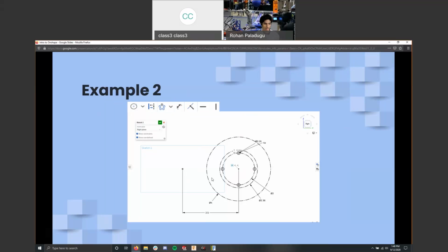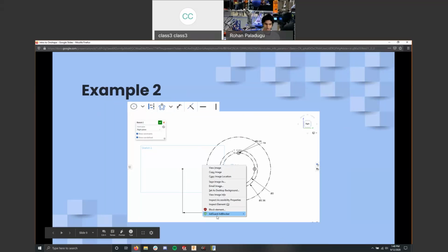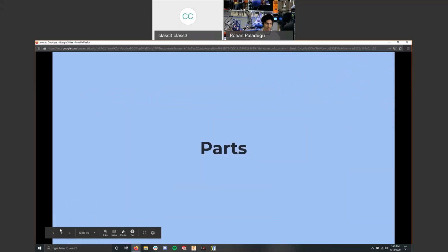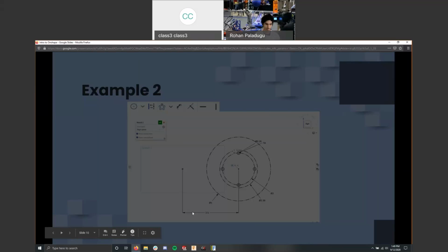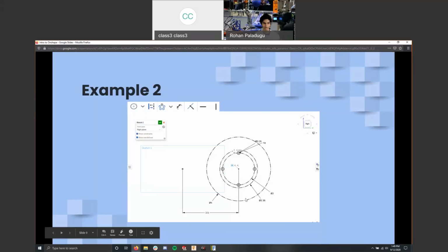And you can see that I dimensioned this off from the origin, which is this little dot, 3.5 inches. Sorry, 3.5 inches. To make sure that it stayed perfectly horizontal, there's an implicit constraint between the center of these circles and the origin, which is denoted here. And then I also used a vertical constraint, and this was not implicit.